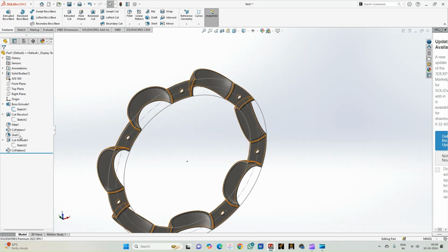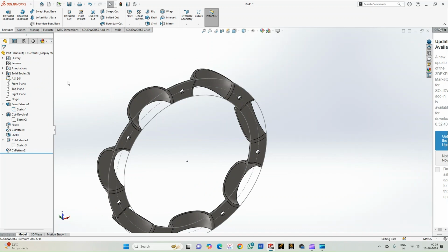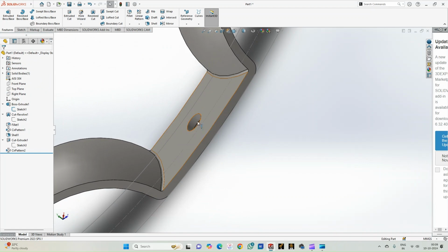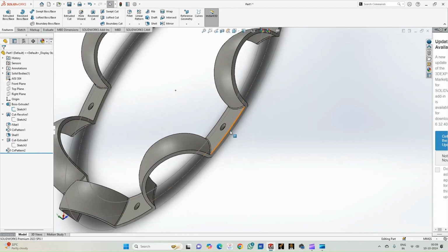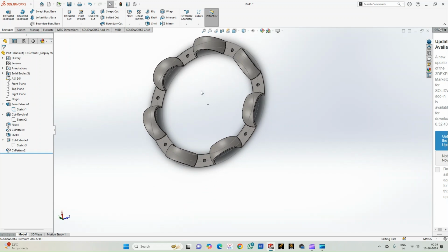And next, the parameter here is, you can just go edit feature. So it is 0.40 mm is the thickness that we have given. So next we have created the rivet hole by drawing a circle again on the centerline circle, and then the diameter is equal to 1 mm, and then we have created the extrude cut, and then we have patterned this extrude cut in between the ball pockets. So with this we complete the generation of the cage component which is used in the ball bearing.